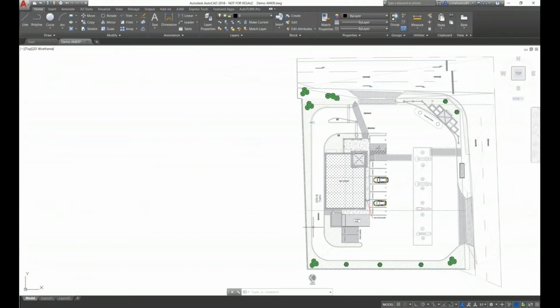The majority of the vehicles that will be entering the drive-through will be passenger vehicles, and there may also be some single unit trucks or smaller trucks that will access the gas station for refueling, but not the drive-through because there is a height restriction of around 2 meters. There are also occasional garbage vehicles and delivery trucks that have to access the loading bay at the back of the restaurant. And also, the site must be accessible by any emergency vehicles in case of emergencies.